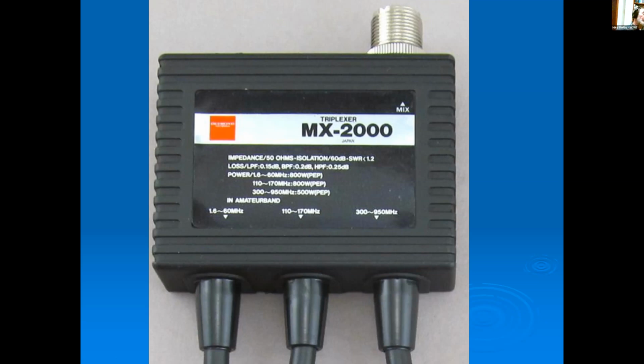And then you have a separate connection for your HF. They'll run it into a duplexer, run a single piece of coax out to under their roof or someplace, and then they break it out from the coax using a triplexer so they can get HF and all your VHF and UHF connections out of it.